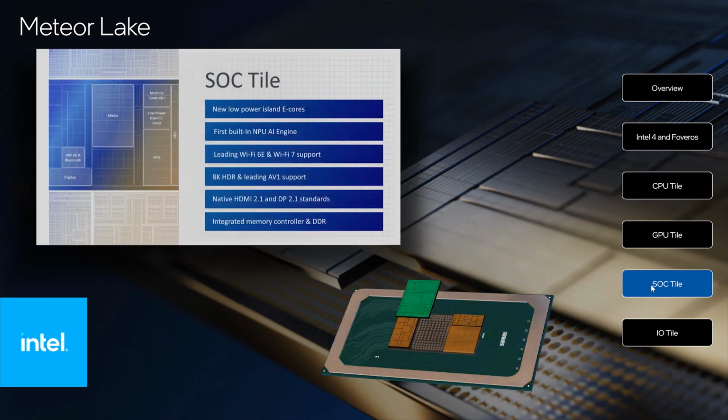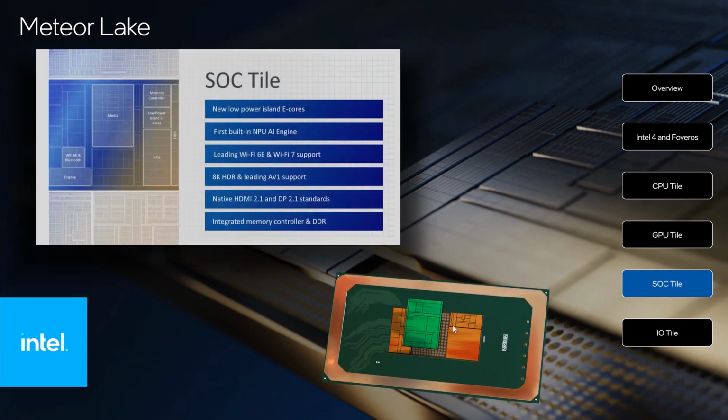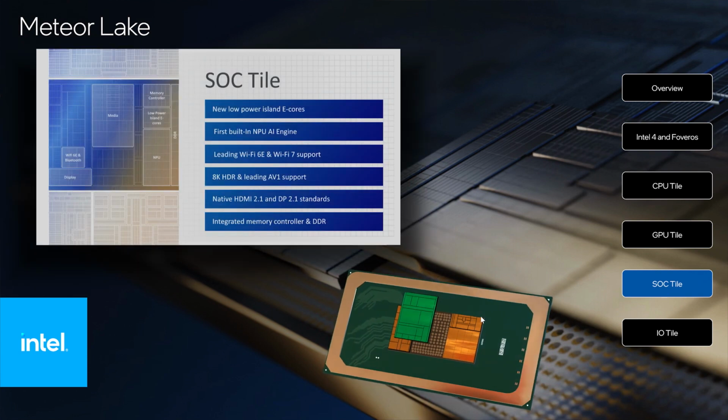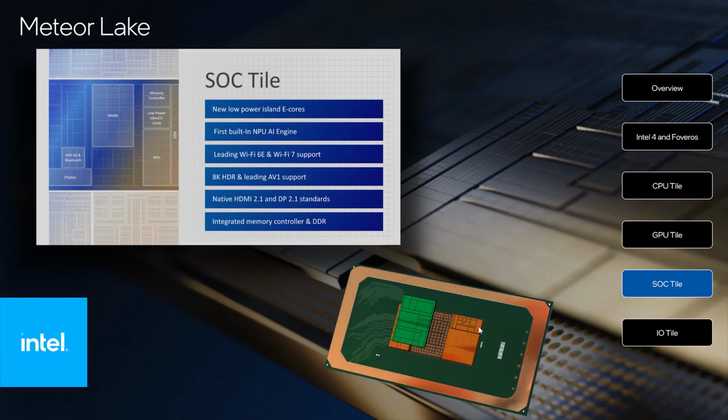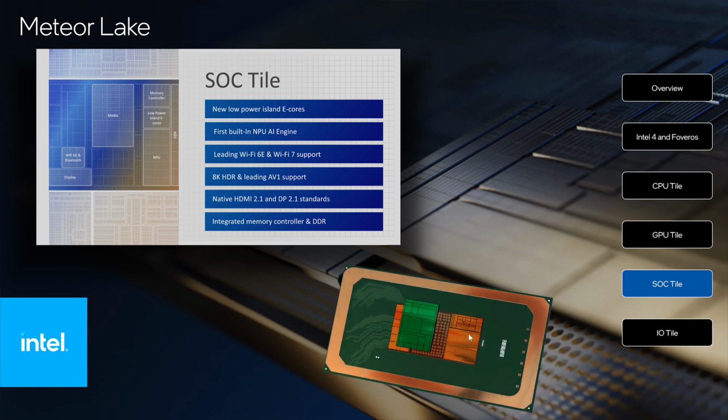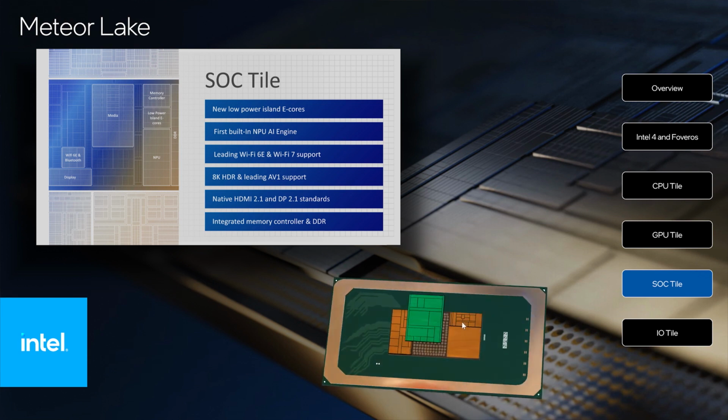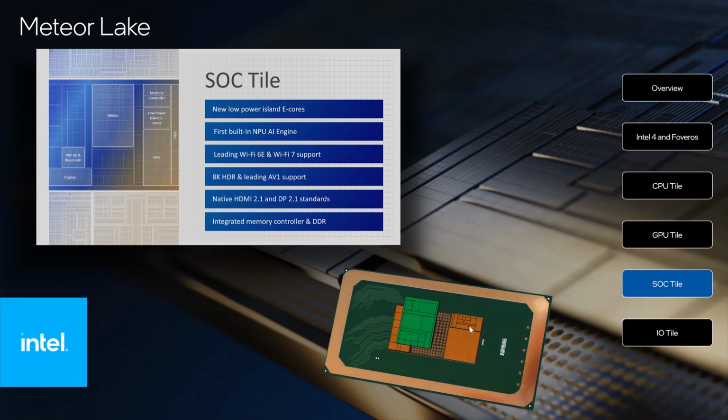In Meteor Lake, we have our SoC tile, right? That's new. So there are SoC-tile-specific algorithms that are part of our enhanced power management, incorporated into Thread Director to reflect to the OS that now is the time to keep the work on the SoC tile, or now is the time to move the work from the SoC tile. Just to give an example on that, right?